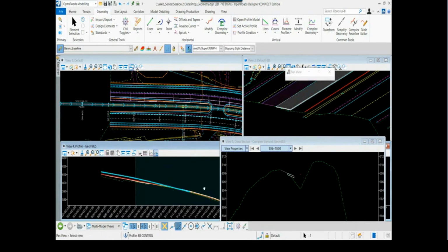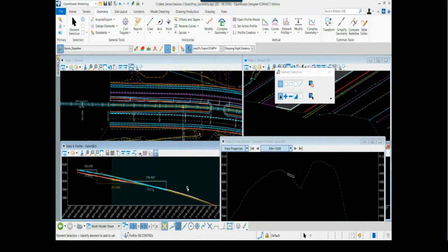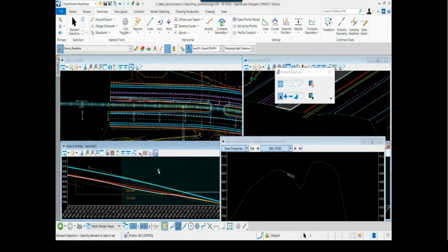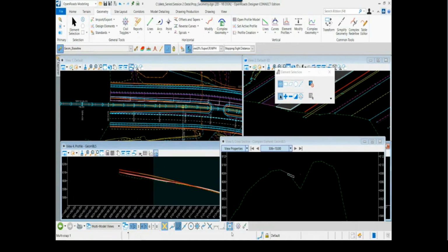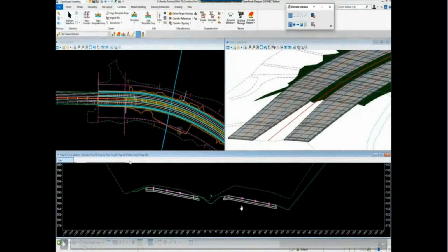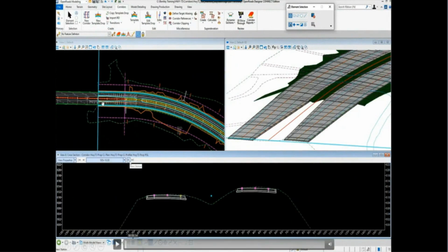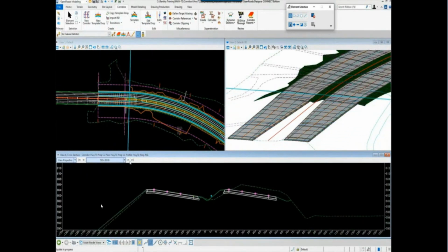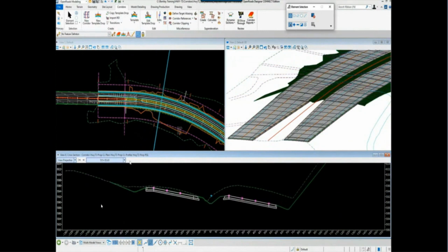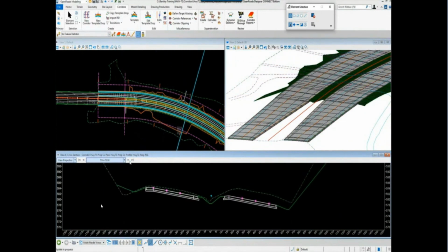Okay? So through this process, I know we're about 5 minutes over, but I wanted to make sure I get that control line in there and show you how I'm accomplishing that. Again, ultimately, the point here for all of this is to look at the objective of where we're going with the modeling next week. So in our session, we created the baseline, the horizontal alignment, and we created the PGL, of course, to control the overall roadway corridor that you see here. You see it in 3D here. And we created control lines to control the horizontal tapers as well as the vertical transition in the bifurcation between the two roadways. And so as we run through this series, as we walk down these cross sections, you can see how the pavement is going to interact when Scott builds this corridor next week, okay?